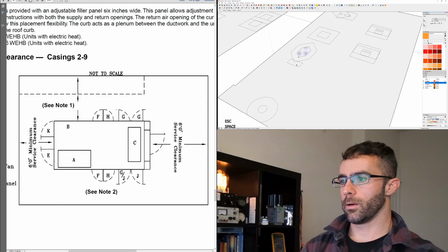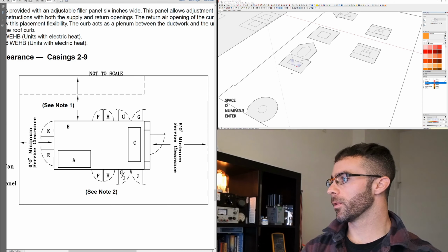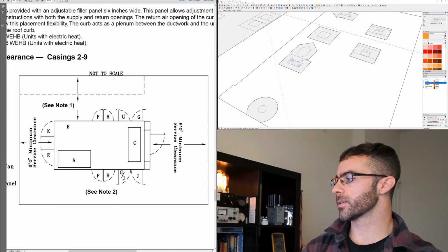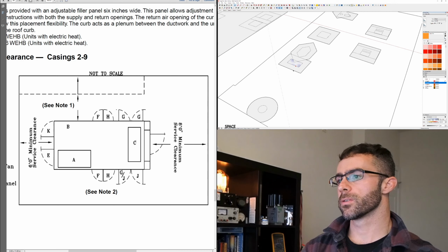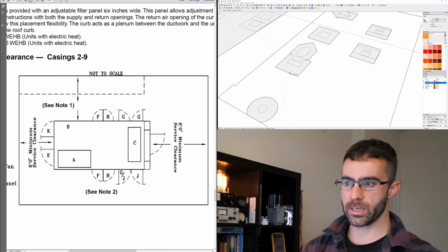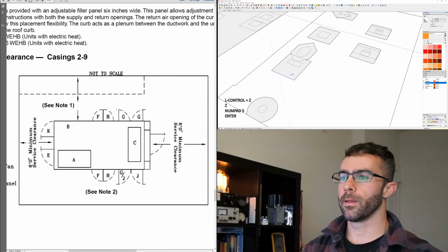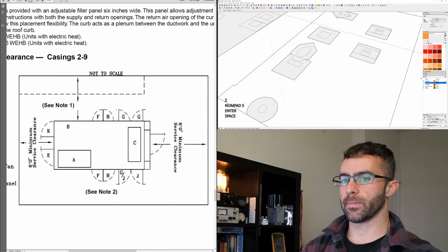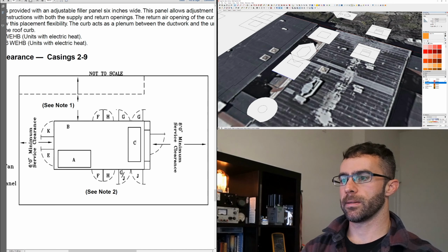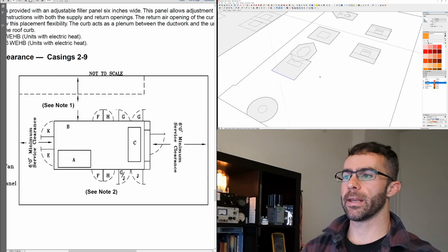And on this face, let's also offset 3 feet. But the one thing to consider was there's some long access required, 6 feet and 8 foot over here. So what we can do is just grab this and slide it on out. Just did 3 feet. Let's do 5 extra feet. 5 feet. And then, we looked at the satellite view. That was just the back end of the equipment. So probably don't need 5 feet of clearance over there. But we won't add any extra.